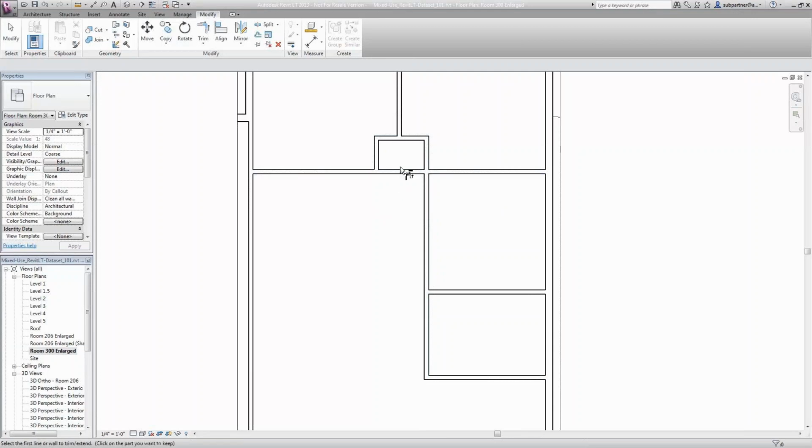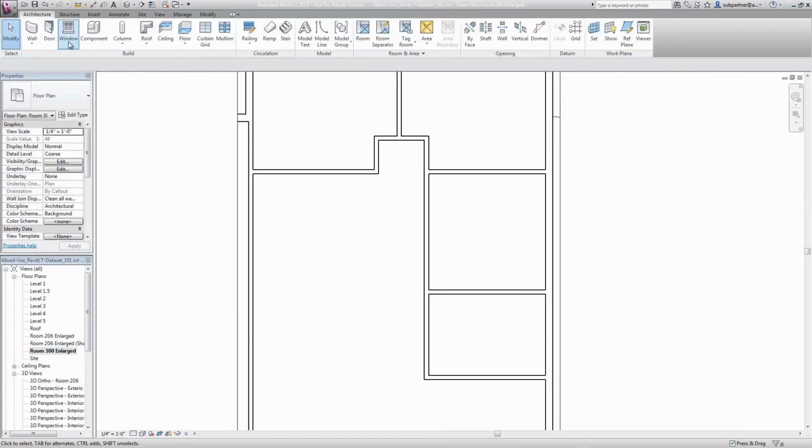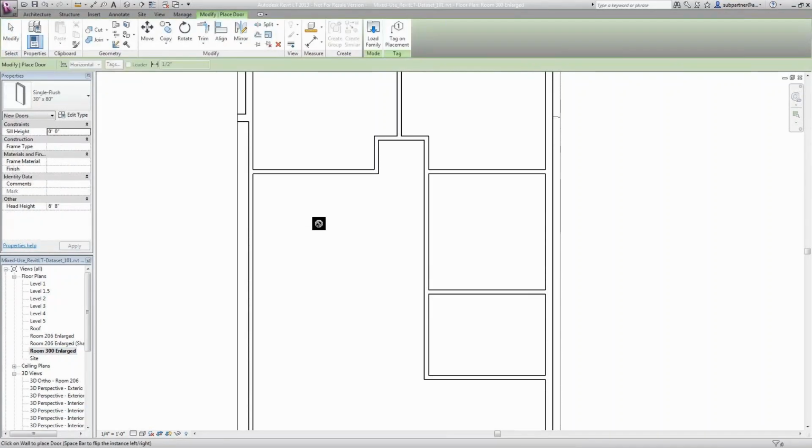Or I can extend, so very easily I can extend to another wall, clicking just the wall where I want to trim it, so I can split it, I can make space, I can delete inner segments, and so on and so forth. So very easily defining what I want to do. And as you can see, the system is also showing me the possibility to define distances by keyboard, so all information doesn't have to be given only by clicking on the screen, but also by typing the value through the keyboard.